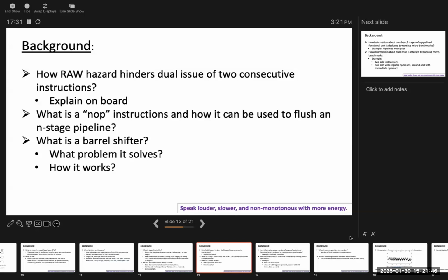Later on you check the actual result of the condition and it turns out to be a misprediction. The branch was taken, which means that you had to execute this part, not this one. But your instructions from this block of code have entered the pipeline, so you have to flush them.